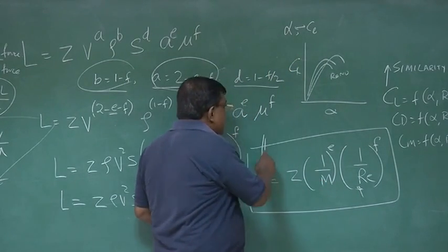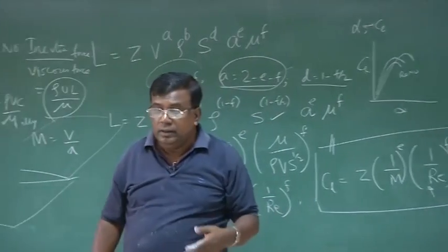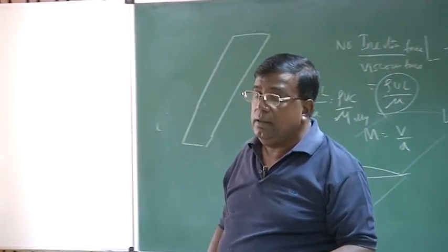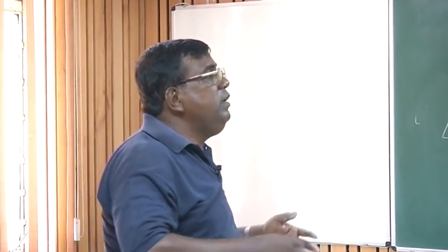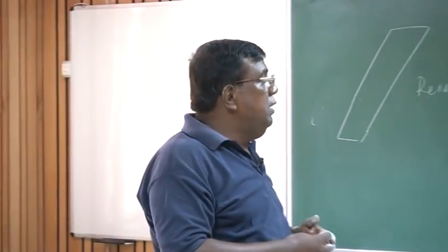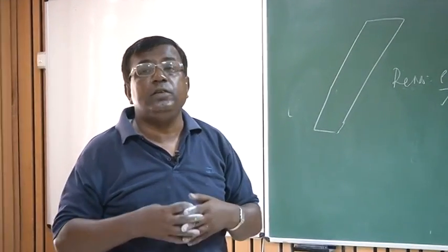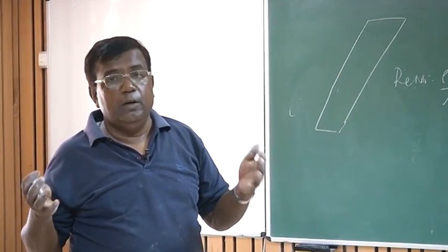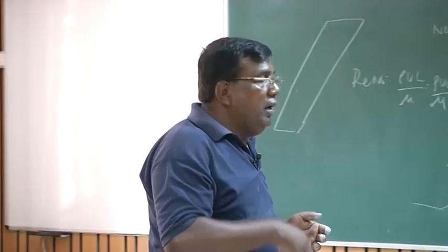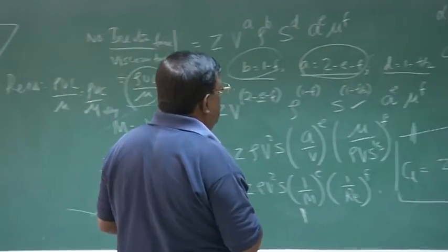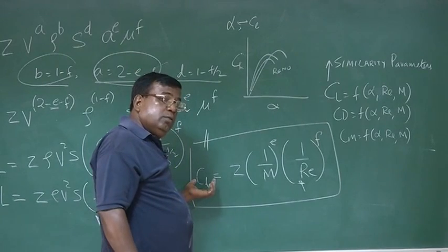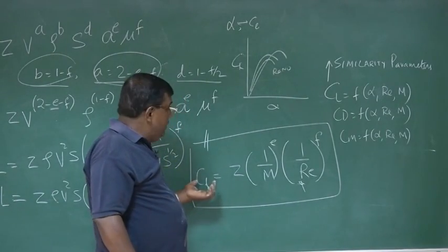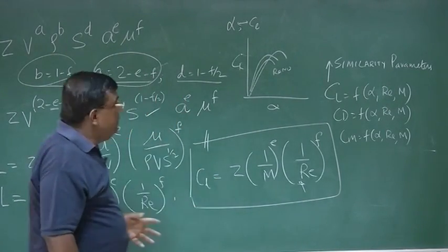And that is why the CL, CD, CM, all these things are also sometimes referred to as similarity parameters. Okay? So dynamic similarity in terms of flow, and similarity parameter means that for a geometrically similar airplane, if you have ensured that it is dynamically similar, I can get a meaningful value of CL through testing by doing scaling. Okay? Thank you.